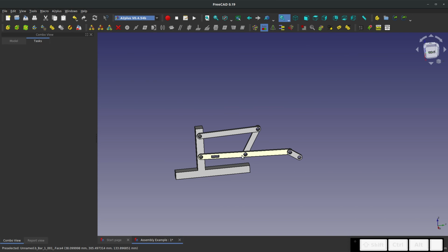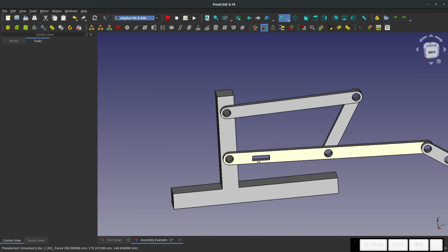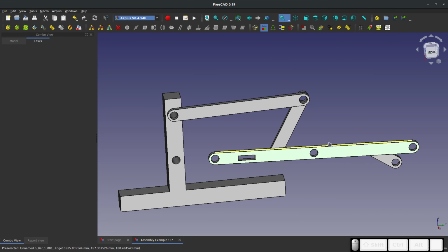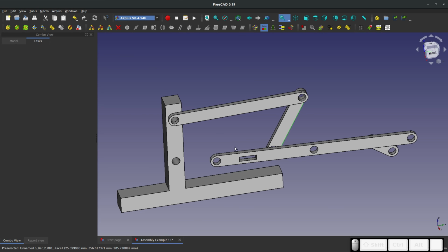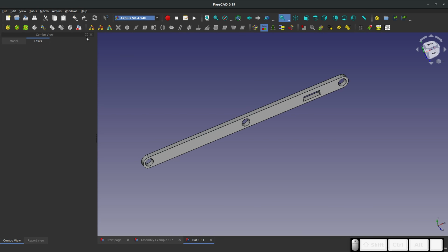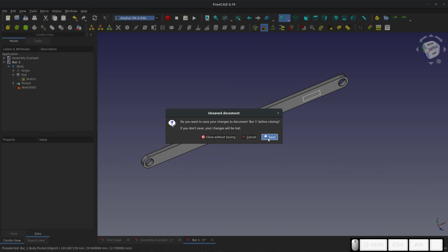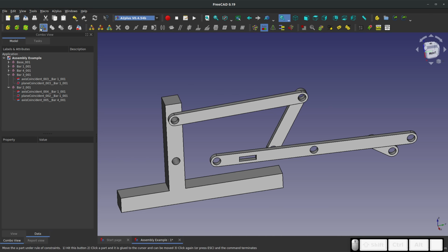Be very careful and plan to not really make many changes in your assembly, or you'll break, just like how I've broken. So if I try to move something, right, things update weird. So yep, just avoid editing stuff. That is really cool that I could add that little pocket there, though, and initially have it not break.